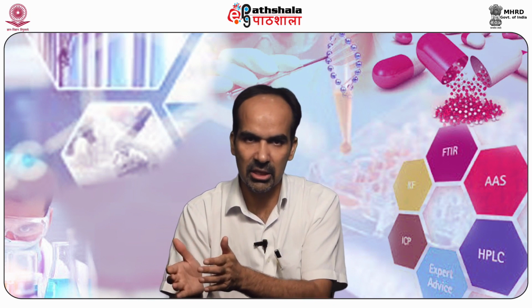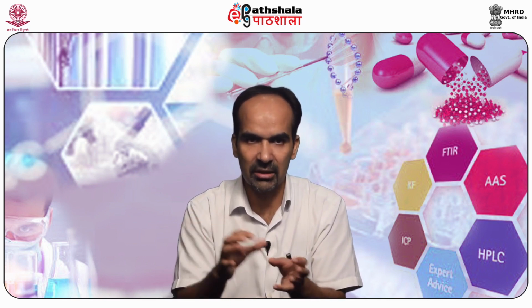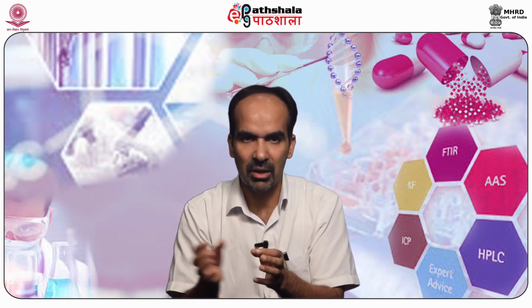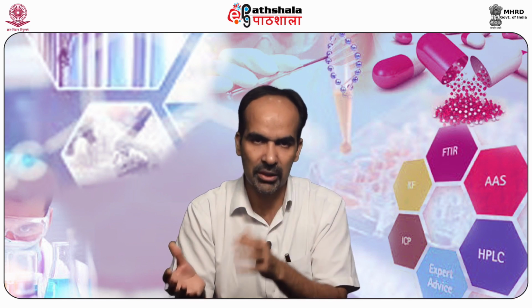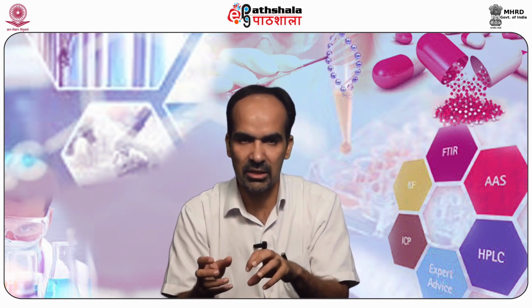It can also be done by generating the steam at some different place and passing that steam onto the material in a utensil or in a flask, so direct contact with water is not there in this case. You generate the steam at one point and then you pass it on, and that steam takes away the volatile content and it condenses in a receiver.